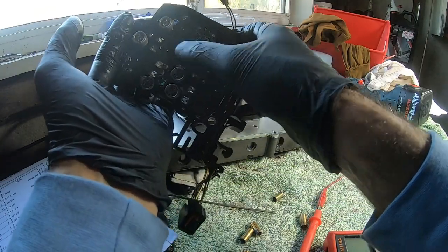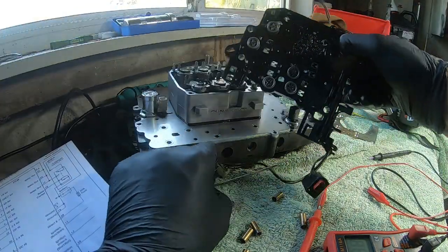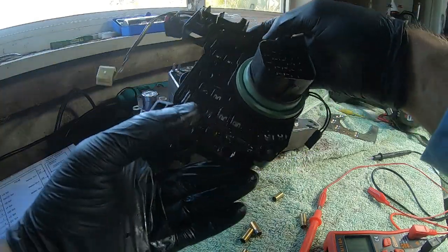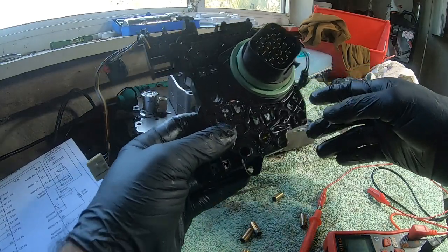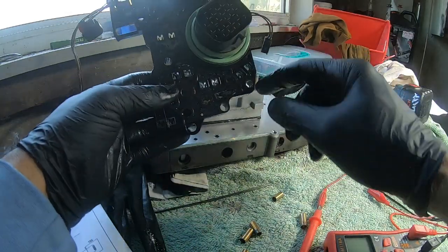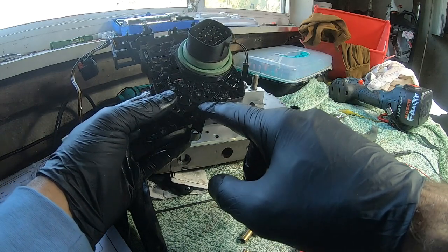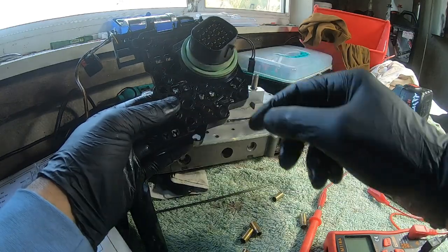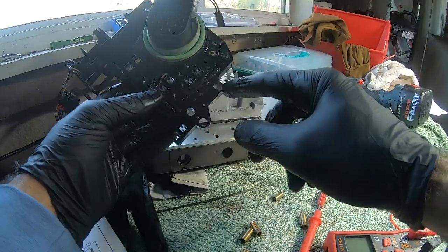So yeah, your pressure switch is good now. So you have to clean all of these pressure switches to make sure that you're doing good. So once you're putting it back, just keep in mind, if you forgot the location of the dowels and the springs, the springs go in those pressure switches which have those small ridges in all of them, and there are 5 in total. While the dowels just go in plain, they do not have any ridges.